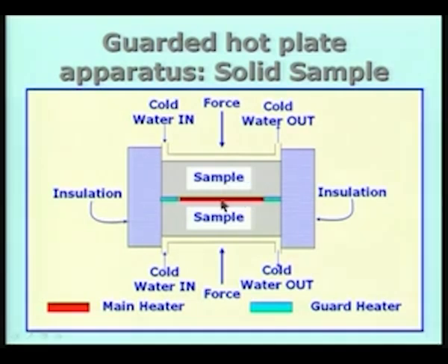And in fact, this figure shows another quantity here, the force. I am applying a force in the direction shown, so that the contact between the sample and the hot plate as well as the cold plate is guaranteed, so that the contact resistance will be very small. If there is contact resistance, the temperature we measure will also contain extra resistances due to the contact resistance,